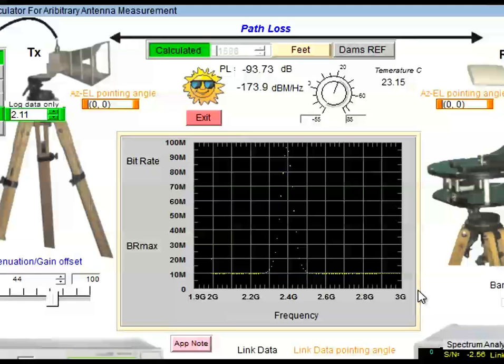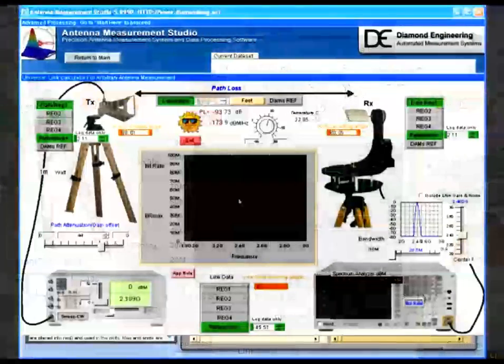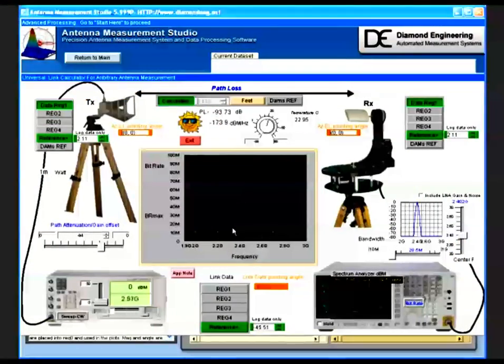If one were to determine the necessary receive gain for known transmit paths, signal-to-noise ratio, and generator power, then we would just deselect the reference button on the receive antenna until that signal-to-noise ratio came in using the path attenuator offset. While our system universally calculates any one of the 4 parameters, there are also a number of other special functions which can be accomplished with the Link Commander.